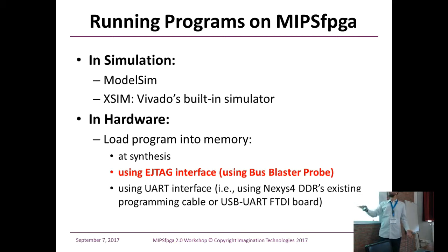On the hardware platforms, while compiling your bit stream, you can pre-initialize your scratch RAM or program memory, or at runtime using the JTAG interface, you can just load code onto the scratch RAM. The third option is the UART, a simple TX/RX pair.